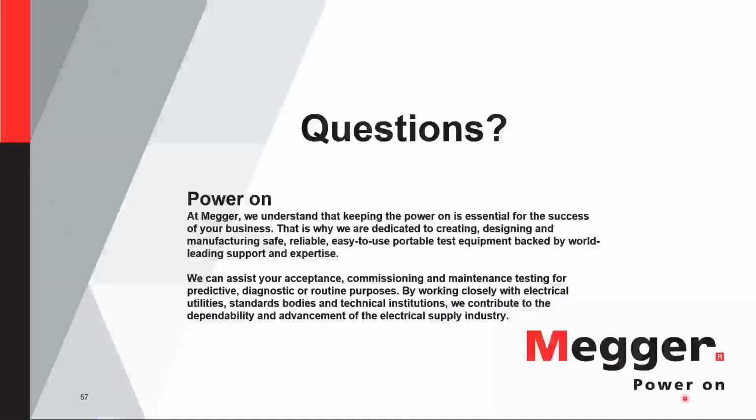Okay, we chose these two questions together because the first one is actually part of the answer to the second question. The differences between when we use D877 and D1816 depend on whether the oil we are testing is just received from the supplier, new oil, or if it's service aged oil. The second criterion will be the application, right?